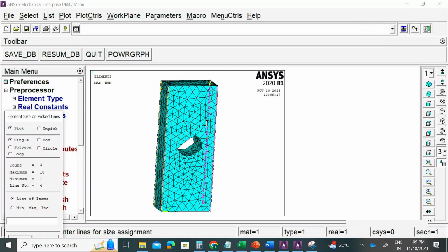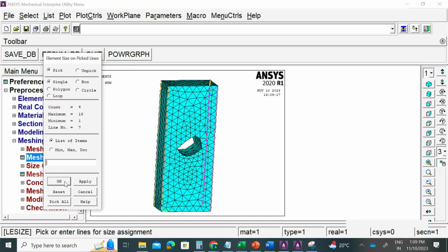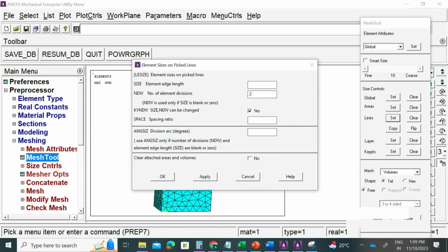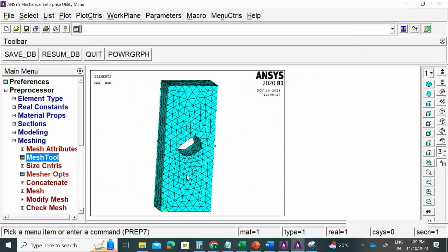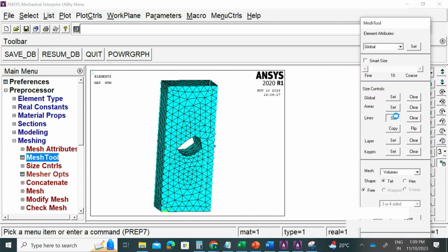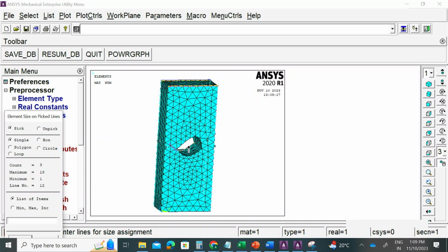So I'm just going to make these guys maybe, I think 20 here is okay. These ones can be done a little better. Oh, I made a mistake there as well. I selected this edge, but the other edge on the other side was not selected. So that's a mistake, right? Hopefully you understand what I mean. It's these two sets of edges. I mistakenly selected just one set, right? So the other side will end up having large elements and one side will have smaller elements.